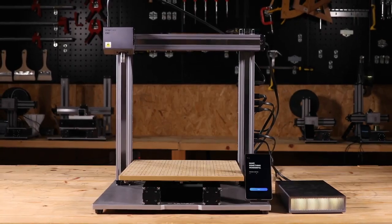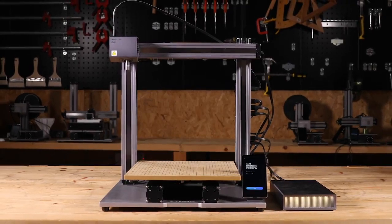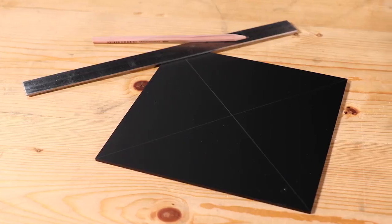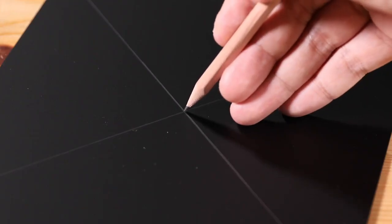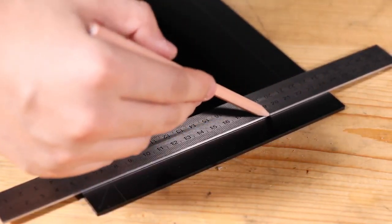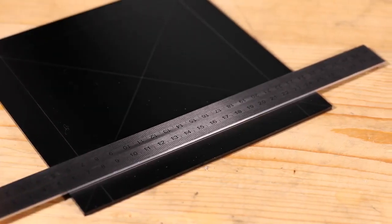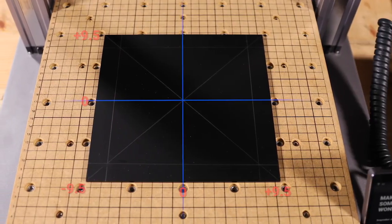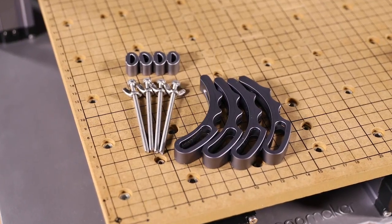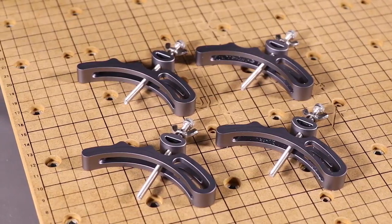In case of collision or carving failure, beginners are suggested to set the carving area around the center of the material. Steps are as follows. First, find the center of the material and mark it with a pencil. Second, mark the carving area. Estimate the largest possible carving area according to the model size and mark it on the material. Or fix the material directly with the help of the auxiliary lines on the platform. Third, assemble the clamp sets. Take the presented accessories, then assemble them into 4 sets of clamps.